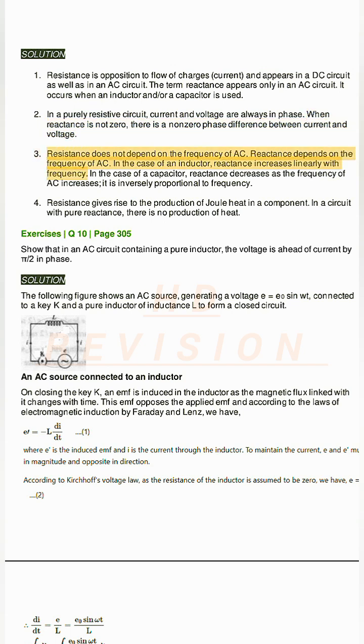3. Resistance does not depend on the frequency of AC. Reactance depends on the frequency of AC. In the case of an inductor, reactance increases linearly with frequency. In the case of a capacitor, reactance decreases as the frequency of AC increases. It is inversely proportional to frequency. 4. Resistance gives rise to the production of Joule heat in a component. In a circuit with pure reactance, there is no production of heat.